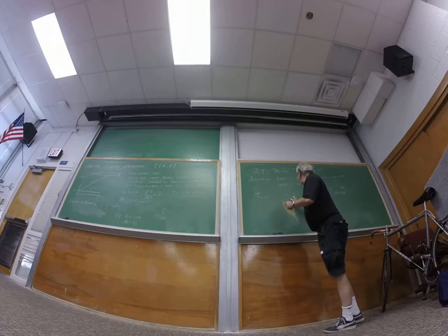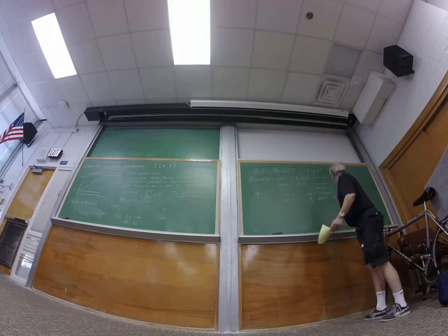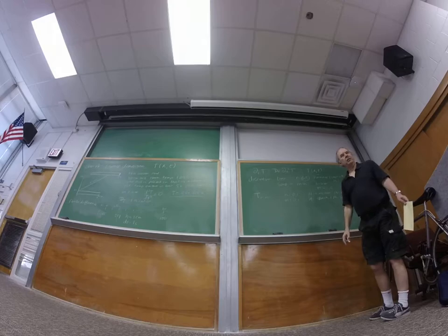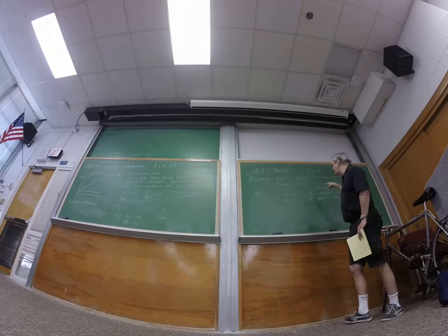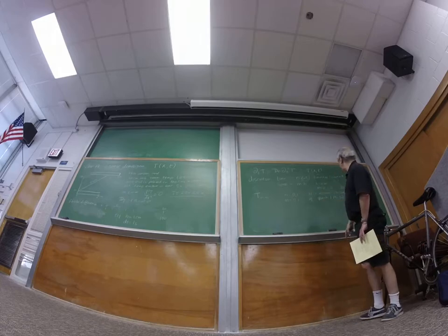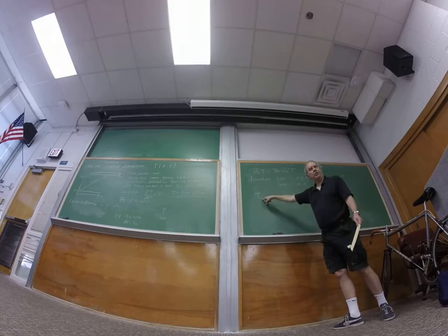And for m, I'd have to start at 0, so those are the space points. And in my first try, m would go up to 30. Okay? So I'd have 31 space points distributed evenly along the bar, and I'd have 101 different time steps. And I'd want to find what the temperature is at all of those points and at all of those times.